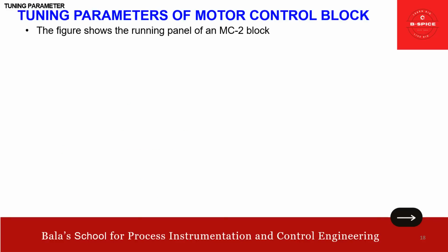Then the motor control block. As we highlighted earlier, motor control blocks are applied to operate motor-driven pumps and motor-operated valves. These blocks may be used to start or stop motors from the operation and monitoring function. Also, combining the motor control block, that is the MC block, with the sequence control function realizes automatic control on motors.